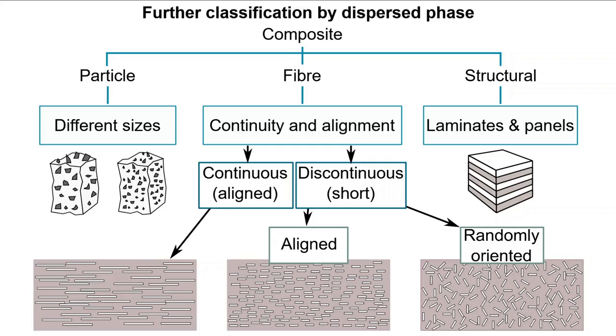The fibers are aligned along a singular dimension and can extend unbroken to the extents of the component in this dimension. Discontinuous fibers can also be aligned along a singular direction or randomly oriented. The degree to which the fibers can be randomly aligned is down to the overall domain and originating mixing technique. For a longer fiber length and a smaller width of domain, then the fibers will naturally align, detracting from being randomly oriented.